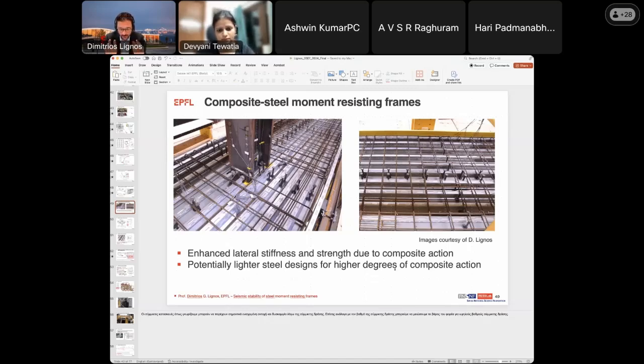The residual stresses will look different if you are cutting the plate versus using the plate directly from manufacturing. But again, I would not think this will impact what the connection does. It would be more of a member issue and how the member behaves itself.